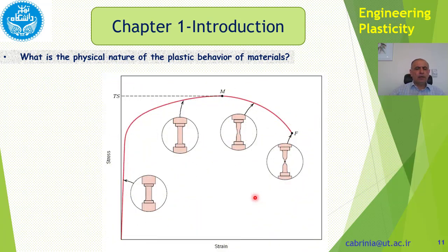Okay then. So from those measurements we can derive values for stress and strain as shown in here. Stress obviously is load over area, and strain is the change in length. So this is the natural strain, as we call it. We have also engineering strain, which is delta L over L0, or L minus L0 divided by L0.